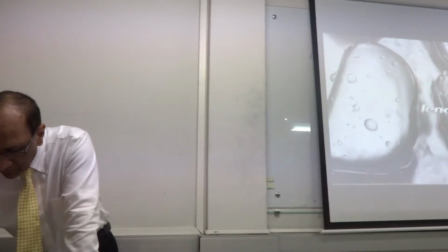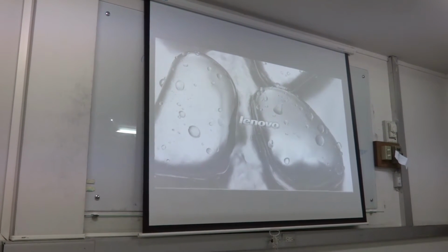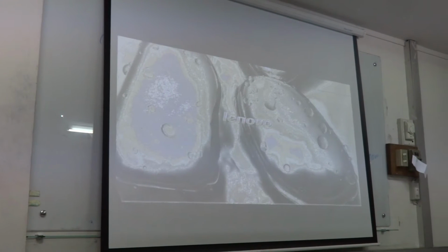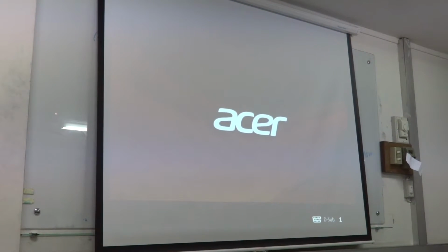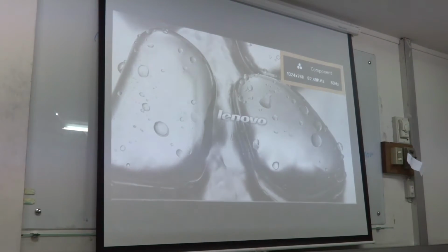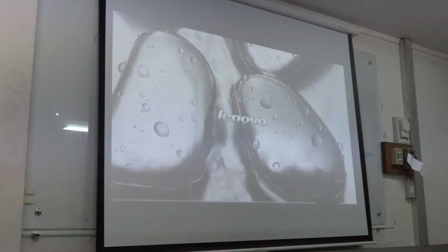So that is what I was telling you about the minimum longitudinal T-bars area. Now this is interesting. When you design for torsion, you not only design these stirrups, you also add horizontal bars along the beam length, because torsion, as I mentioned to you, has both components. It produces shear and it also produces tension. So to take care of the tension, the longitudinal bars must also be calculated and added to the top and bottom bars of the beam along every place.